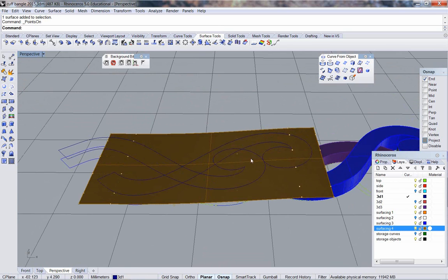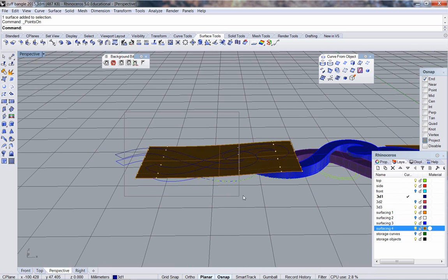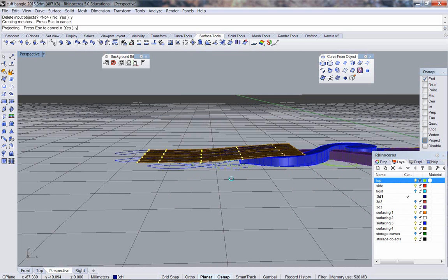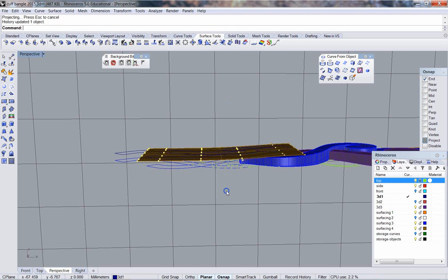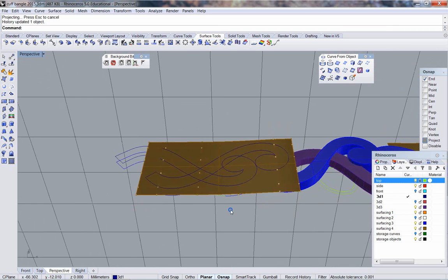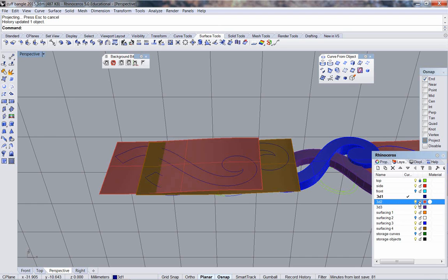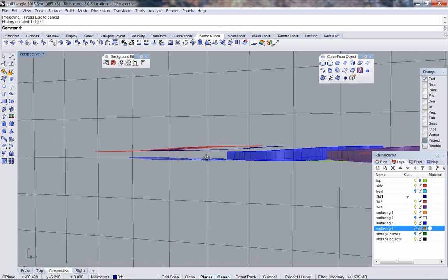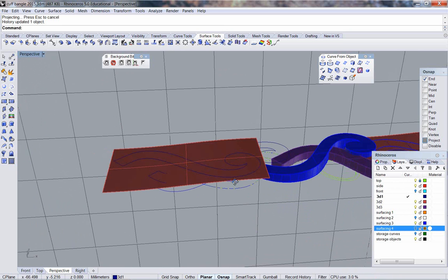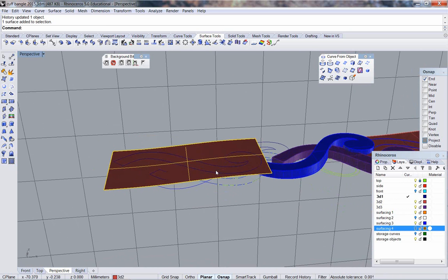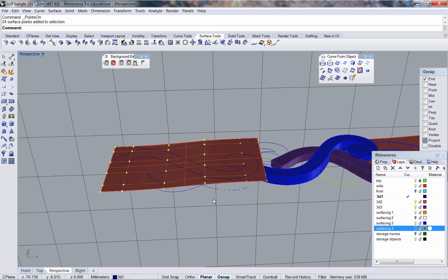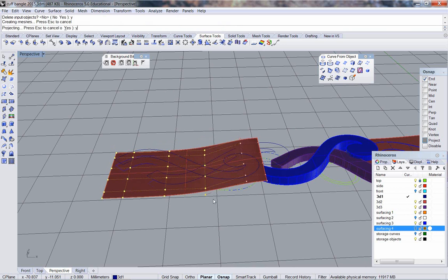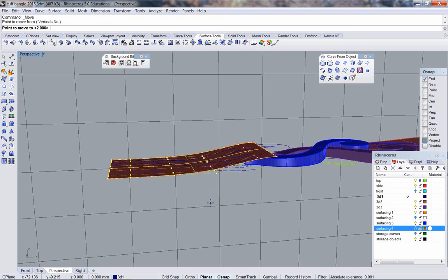This is climbing up, so it won't matter if this gets even lower here. I want as much at 2 millimeters as I can get. Front C-plane, 2 millimeters straight up. Okay. This is more of a challenge because I need to keep the elevation here, but I can lose that right through there. I'll do the same thing here. Top C-plane can project, front C-plane, so I can move back up 2 millimeters.